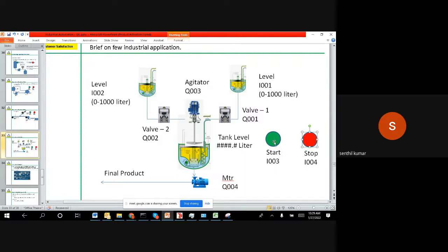Initially, when I push it, you open this valve first, and this valve can open. Once it is open, we can simulate this level slowly, because once you open it, water will go down; in a real plant the level will come down. Whereas in your logic, when you open it, the level won't come down. You have to simulate it, because it's a simulation, not an actual plant where the level really comes down. So once you open this, I can simulate this level from 1000 to 499.